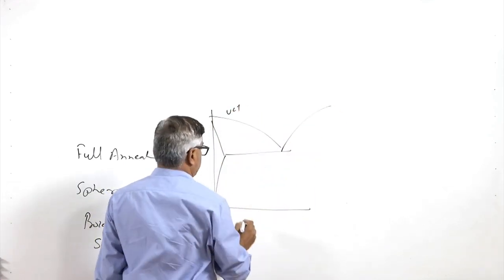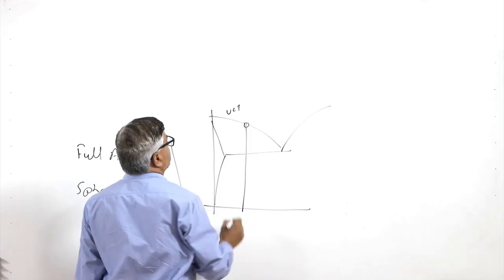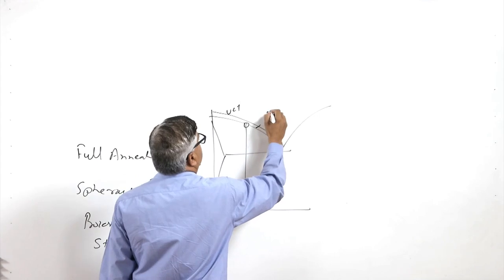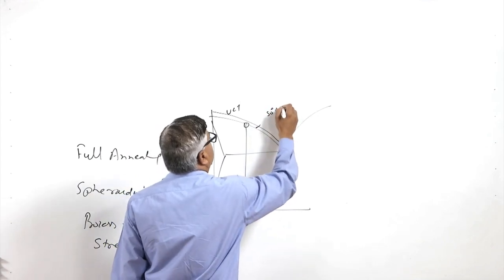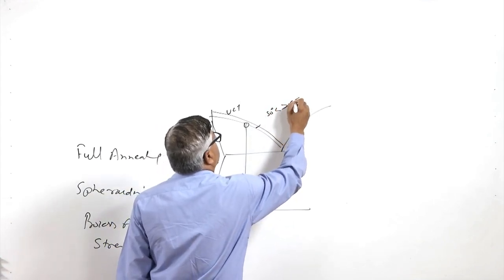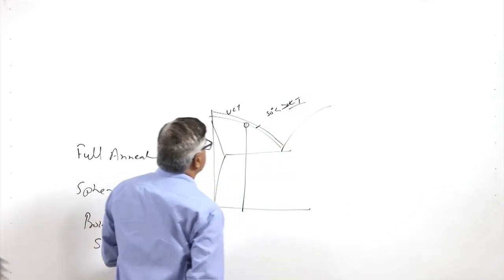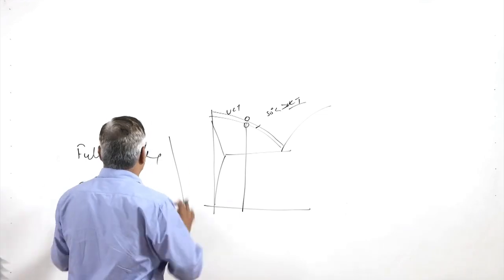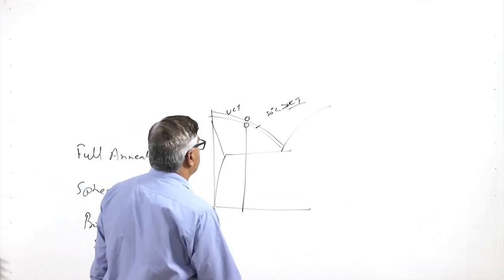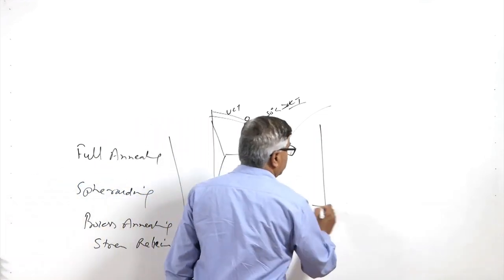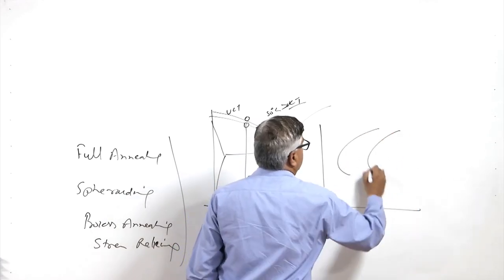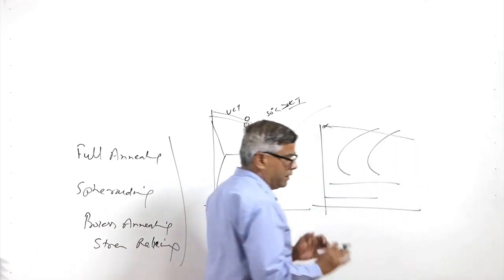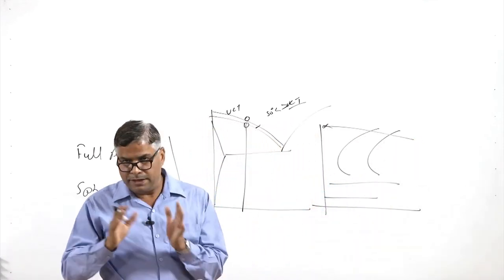So, with regard to the iron carbon diagram, this is the upper critical temperature limit. If we take one particular composition of the steel, it is heat treated at about 50 degrees centigrade above the UCT for a given steel. We will be heating up to this temperature for homogenization purpose, as per the dimensions of the component to be heated, and then, considering the CCT diagram for the annealing purpose, we use cooling at a very low rate.